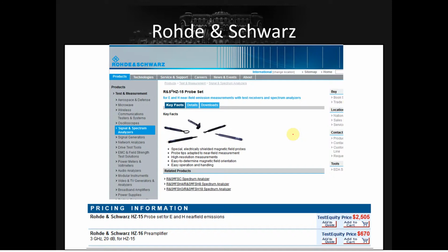We can actually use an electromagnetic probe, and we just put the probe near the chip. There's even cool demos I've seen with CRI, for example, doing a magnetic probe over a regular smartphone, and it works through the smartphone casing. So it's definitely not the case that you need to modify the hardware. And if you want to play with a magnetic field probe, you'll need a magnetic field probe. It should not be rocket science.